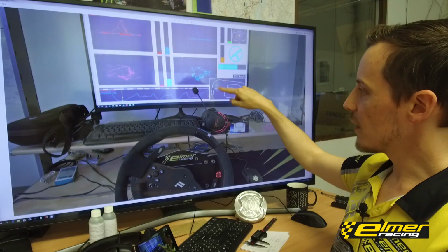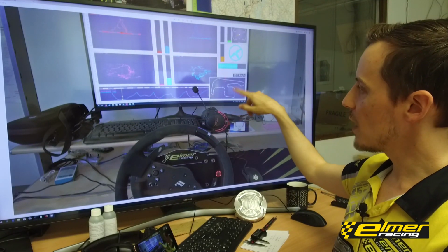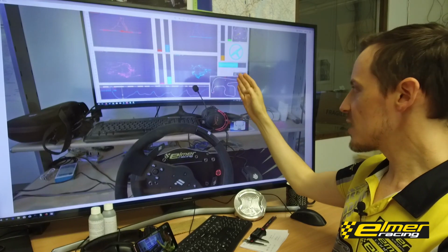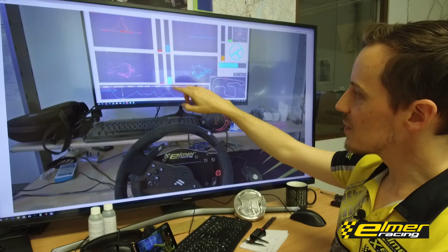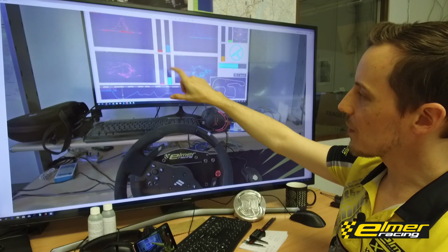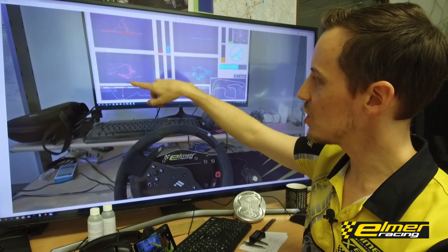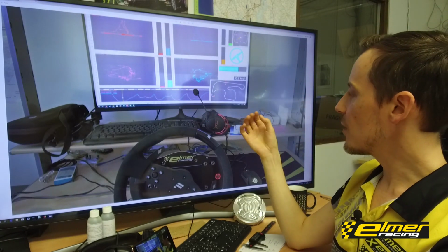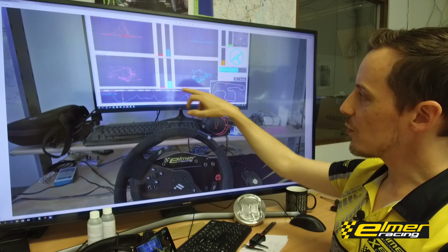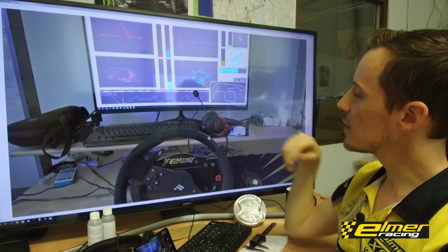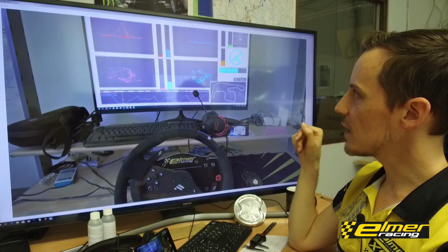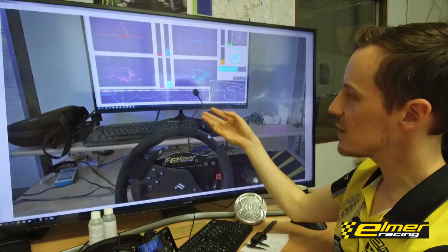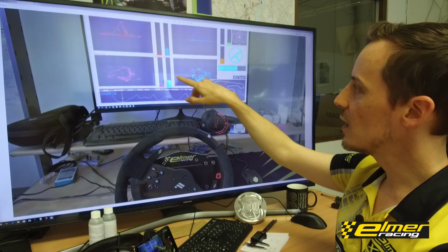We can drag this through the whole lap and see, okay, we have some problems that the car is pushing in some corners. So we can check out what our wheel loads are and how much force in which directions the wheels are applying, or using the tire friction in relation to the lateral, or the vertical force applied, and how that's being used in which direction at which tires.